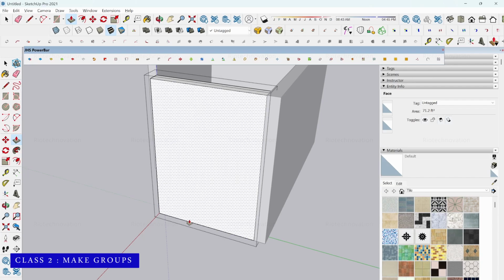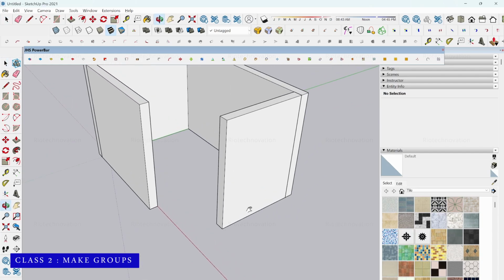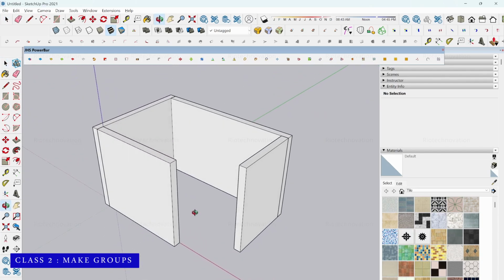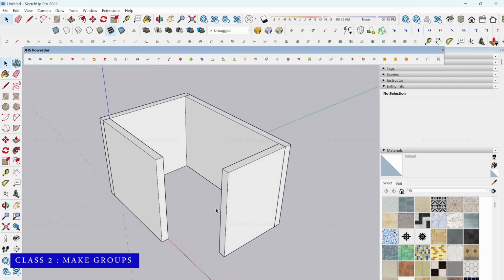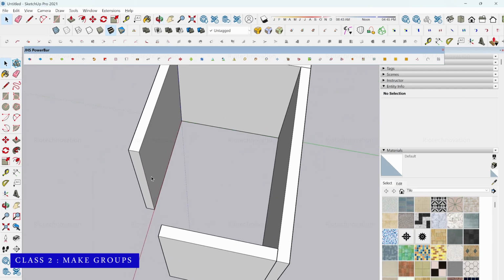This is the next method. So I told three methods to do extrusion. First, you can put the values by just providing the measurement. Second one, I told, by using reference surfaces. Third one, by double click for whatever the previous extrusion was. So these are the basic three methods to do extrusion or push pull or whatever you need to say, right? So before winding up, I'll do one more thing here. Better we can do it here only. So I think this is clear for you.